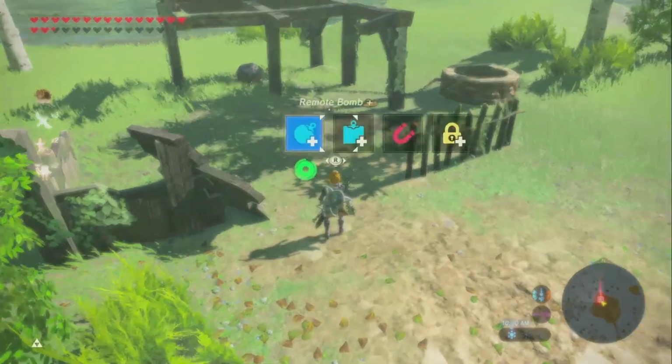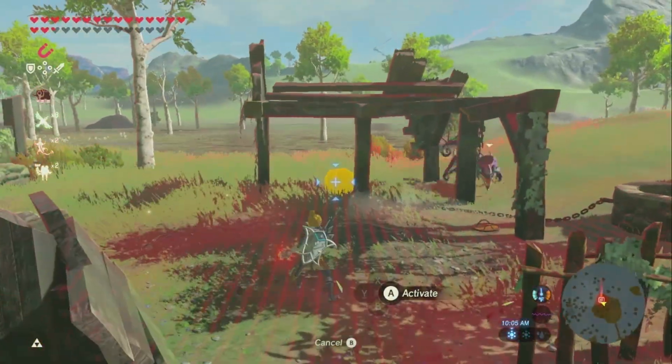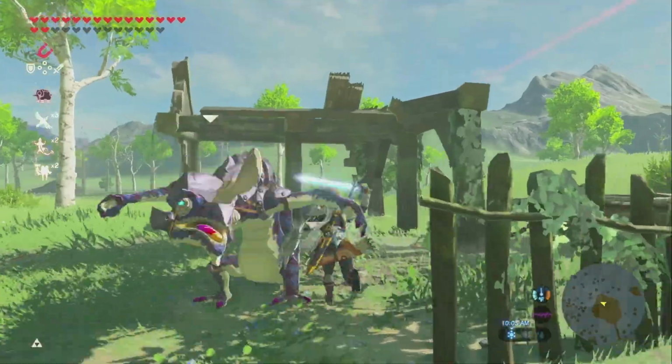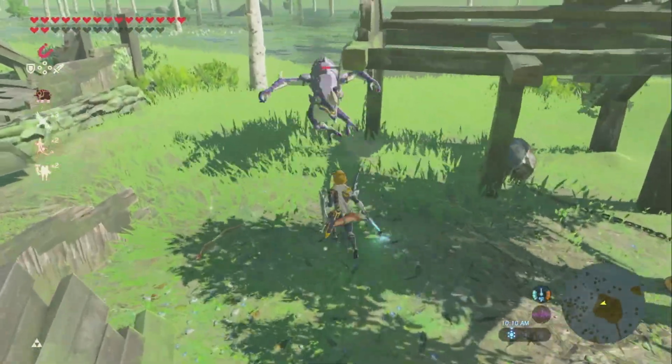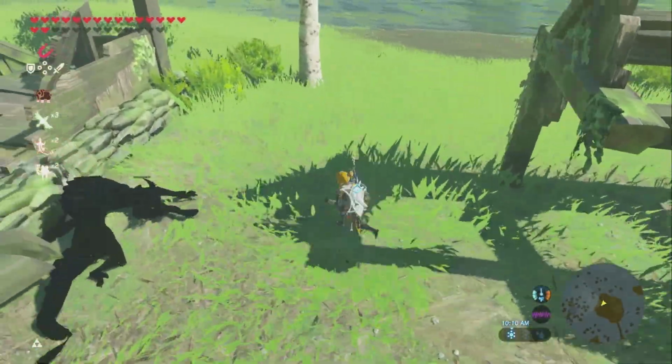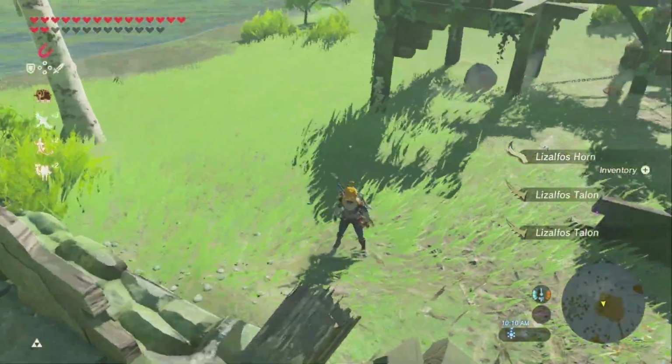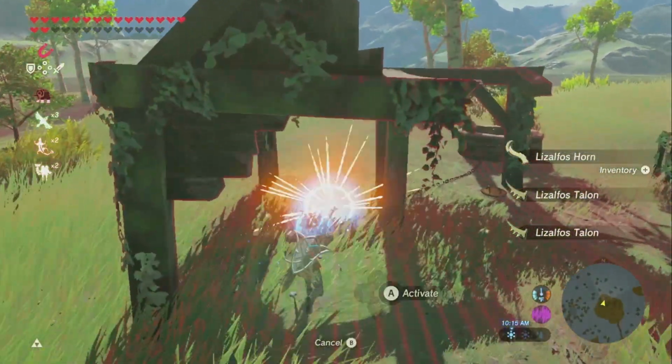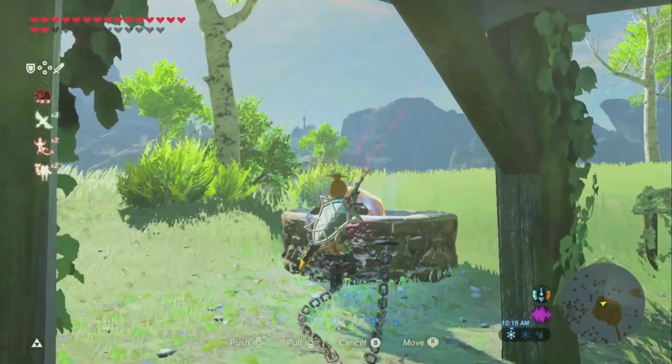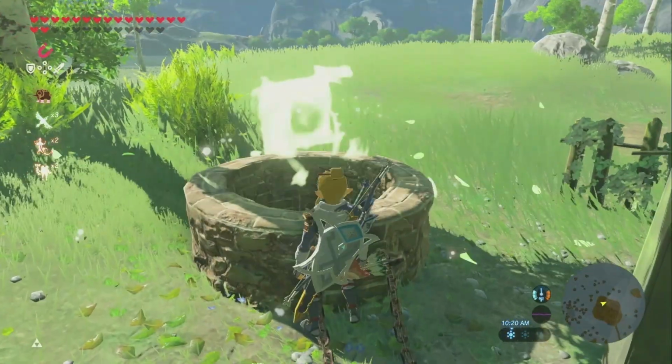TPR will open and release water when temperature exceeds 210 degrees Fahrenheit or 99 degrees Celsius, or 150 psi. Don't test relief valves, as most often they will not shut off again and will continue to leak. TPR is a safety device.